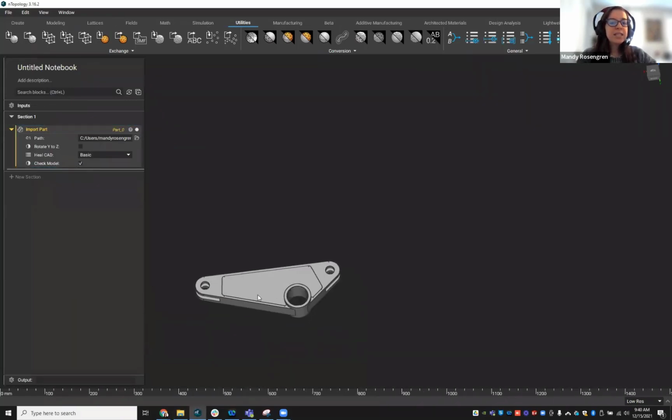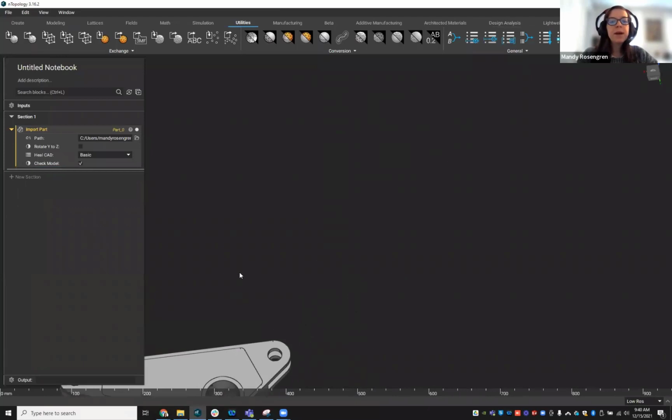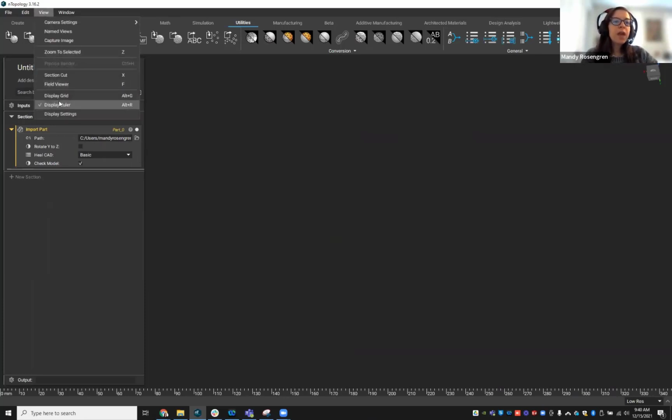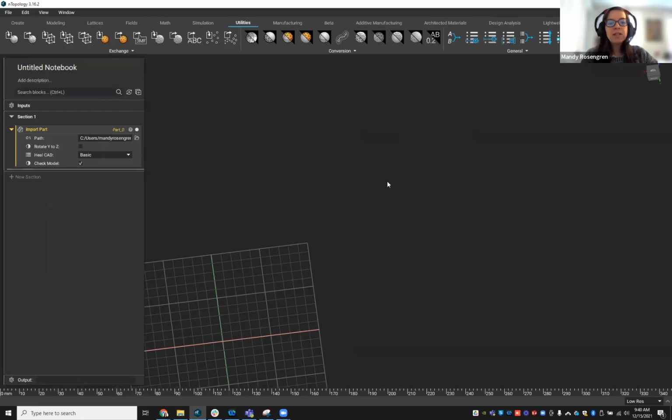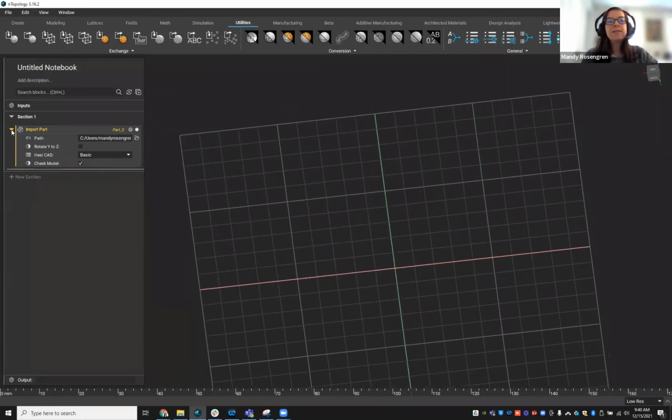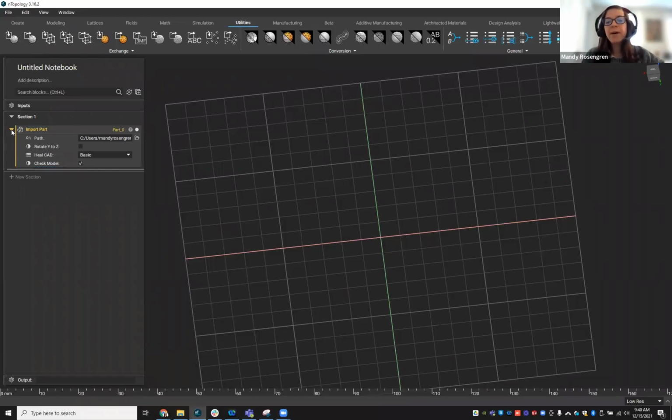And actually, in this instance, I was able to see this, but if for some reason you don't see it, part of the reason might be, one, double checking that you have that visibility on. If you just brought that in, the visibility should be on. Then also what you can do is go to View and look at our display grid. Sometimes if you're really zoomed into that display grid and your CAD part is not centered at that origin, we won't see that immediately.